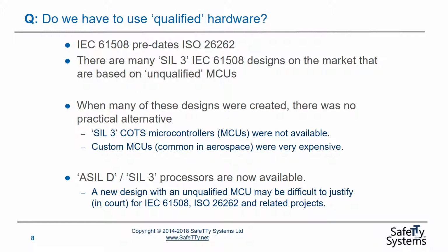The world is now a different place. There are various ASIL D processors available. Starting a new design with an unqualified microcontroller may be very difficult to justify in court for IEC 61508, ISO 26262 and related projects. The bottom line is it's almost always necessary these days to use qualified hardware components in your design.